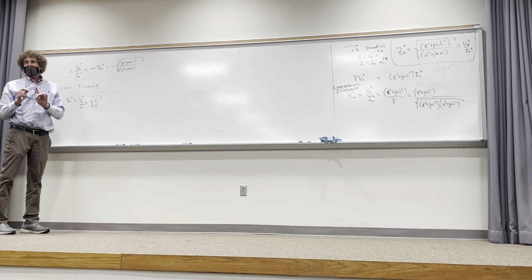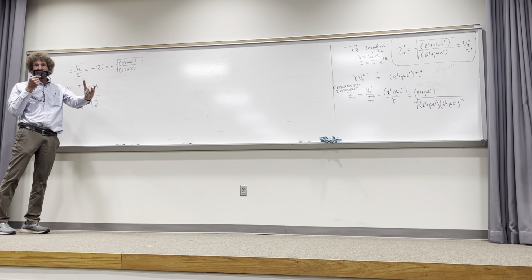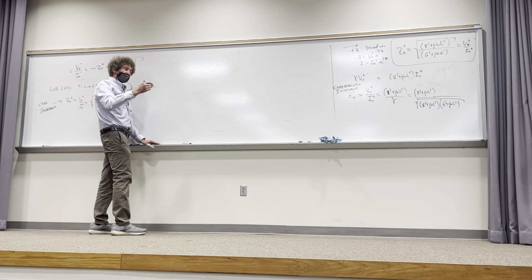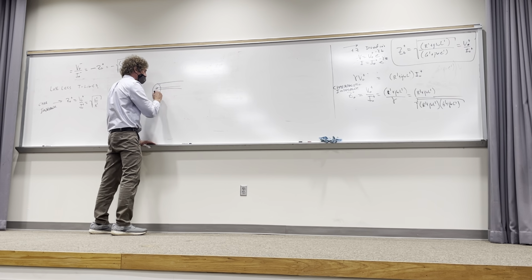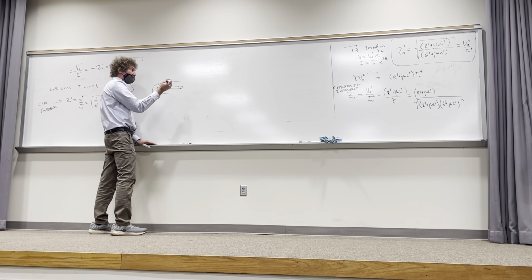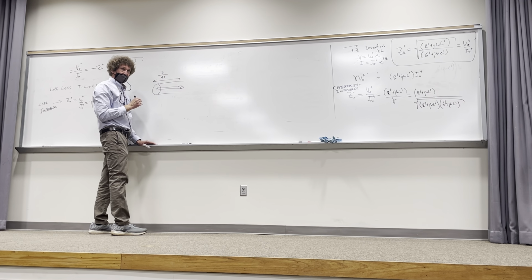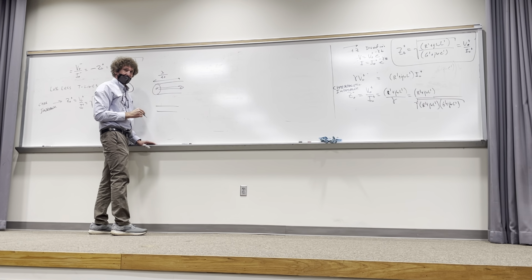There is something that has to be said for how long a line has to be before it actually has that impedance. And here I'm just throwing something out that's a little further down the track. If you had a coaxial cable as such, and it was lambda over 40 long at the frequency, it isn't 75 ohms between these two. Now this is just a straight piece of wire, two straight pieces of wire. You all follow me on that, class?